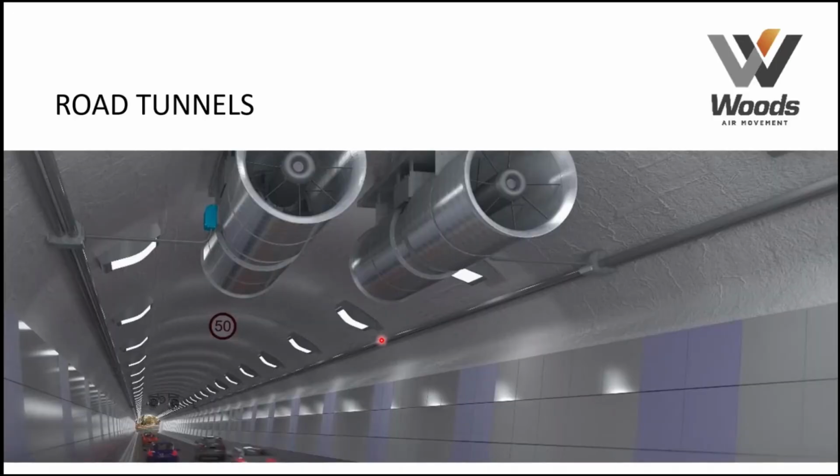So the second main application is road tunnels. This is probably where we started our business in terms of tunnel ventilation, and for this particular application, when it's road tunnels, we're talking about dealing with pollution and what to do in case of a fire or emergency. These systems and the way they operate and the way they're designed has certainly changed in the last 40, 50 years. So I'm just going to quickly run through the different types of ventilation, but what's shown here is a system using jet fans. This has certainly become the most popular method of ventilating road tunnels, but there are some limitations or issues associated with it which you have to be mindful of.